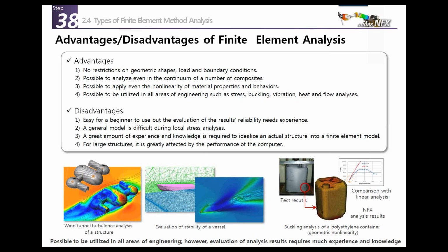More than that, if you have a very general model, it's difficult to get the local stress analysis, and it requires a great amount of experience and knowledge to idealize and structure it into a finite element model. For a large structure, it's greatly affected by the performance of the computer, so you also need a very good computer if you have a large model. So these are disadvantages.